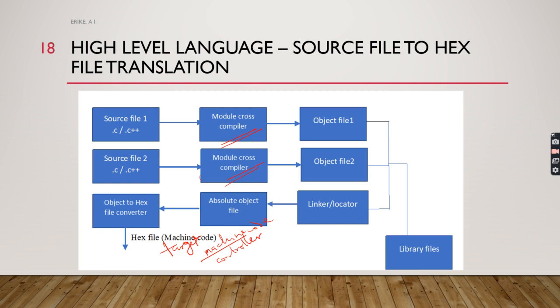Even when you are developing this, in the IDE that you'll be using, before you start writing your code, you will first of all select the particular processor that you are writing for. And there could be header files, the library files, that you will need to use to indicate that you are actually writing for this particular controller.